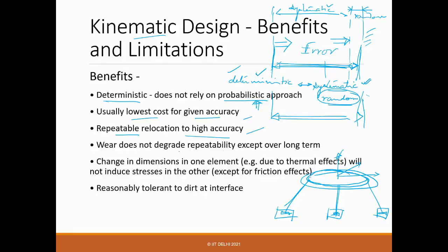Wear does not degrade repeatability except over the long term, right? So even if there is wear, it will still be repeatable. Only over the long term do you have to adjust. With the kinematic clamp I showed you earlier, you can easily visualize that changing dimension in one element due to thermal effects will not induce stresses in the other.